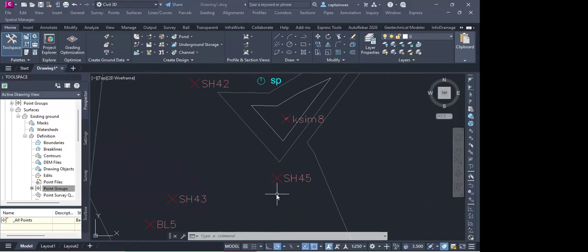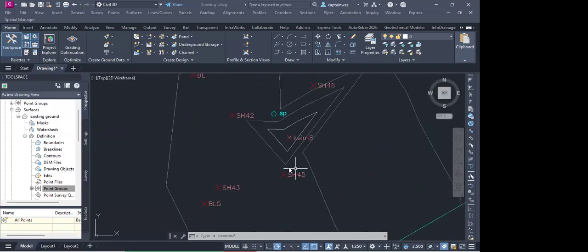The next thing before we continue, because I'm seeing we're having a lot of information and we can't make sense of it, is getting to georeference your drawing. When we were picking these points, we were told that this is the coordinate system you are using. That was the ARC 1960 UTM, right? And the zone, we were told the zone is 37 south. And I think in the previous class I was able to show you the zones.